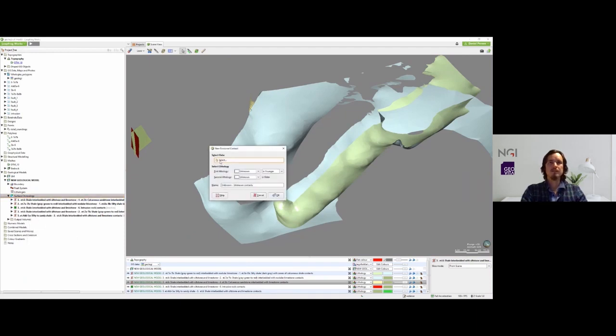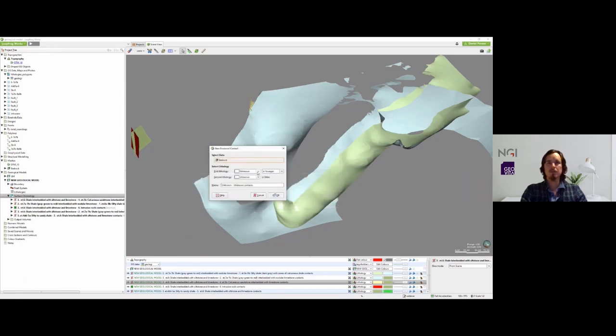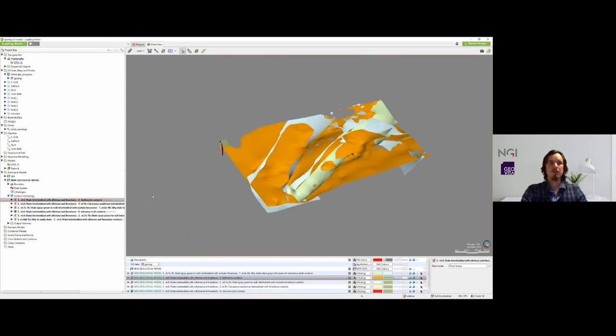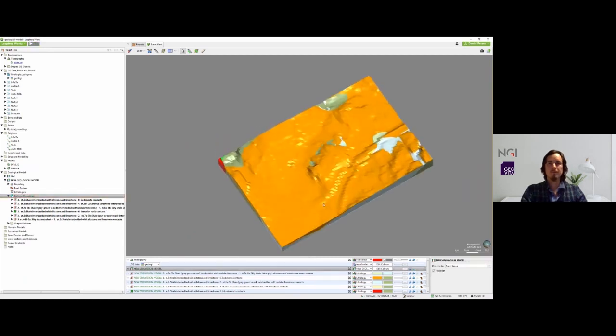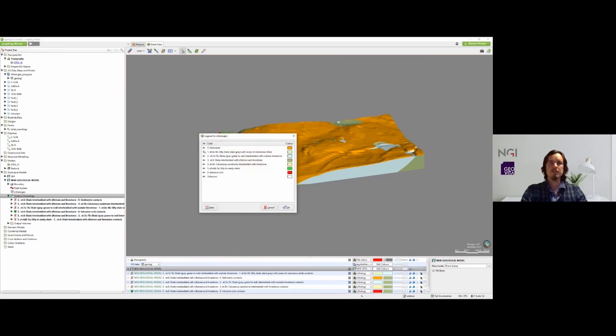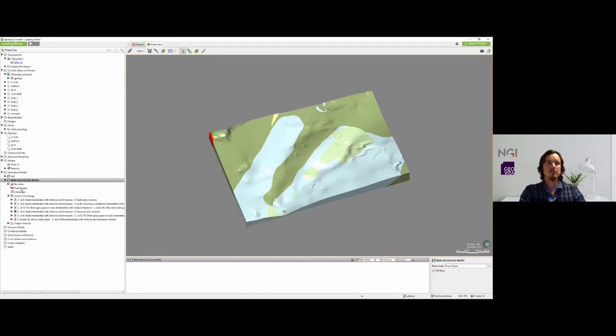Let's add the surface. This one will add from the bedrock mesh, which is created from total soundings. And the soil is the youngest boundary in the model. Okay, so now we have all our surfaces, and now we gotta open them and activate the surfaces to build the volumes for the model. There we have the model. We can turn off the sediments. And then we have the lithological areas.